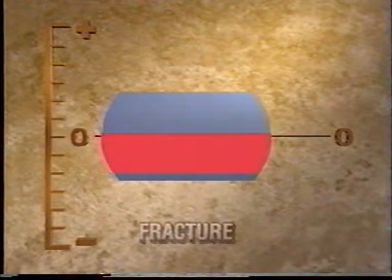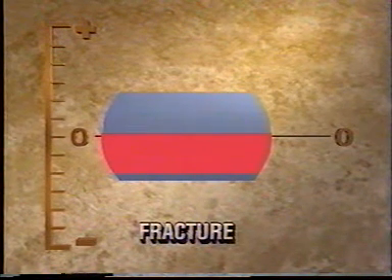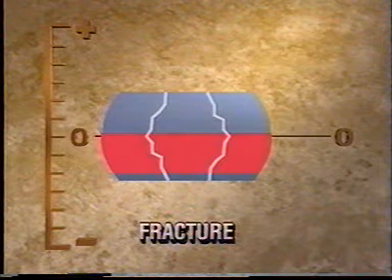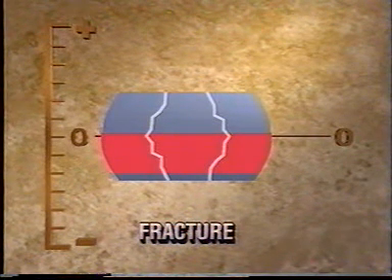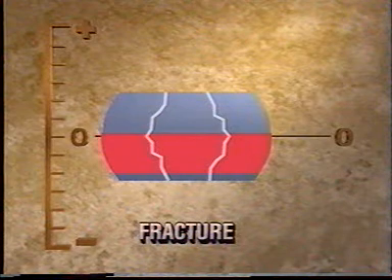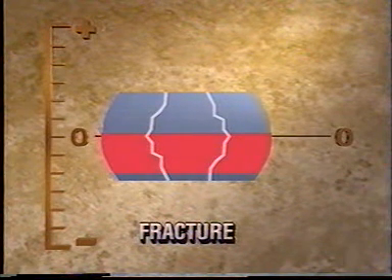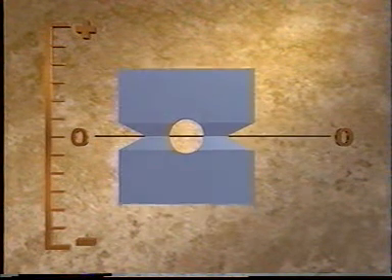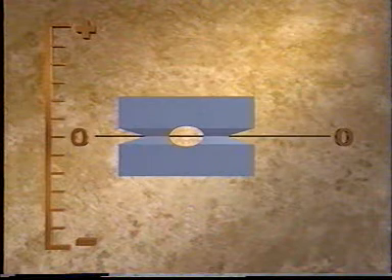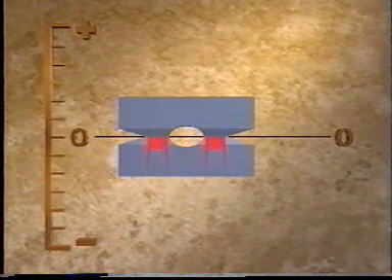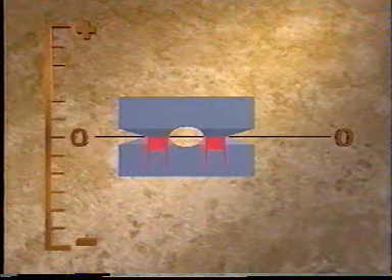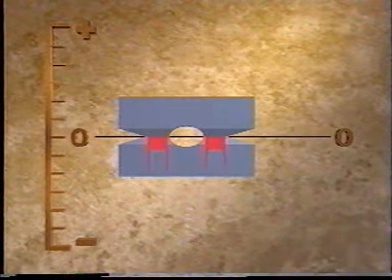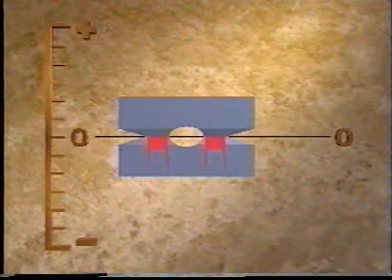In brittle metals, however, a single load fracture can occur parallel to the direction of the compressive stress, but this is caused by the circumferential tension stress perpendicular to the compression stress. In both ductile and brittle metals, the compressive stress can be concentrated at the tips of notches or at internal cavities, and these stress concentrations will be in the negative direction because of the compressive loading.